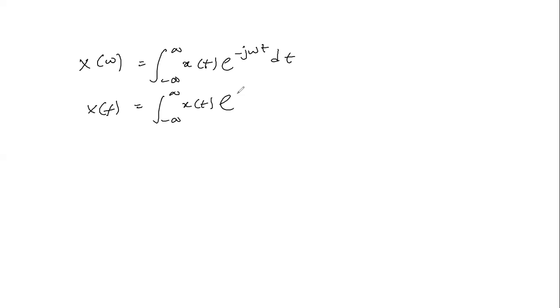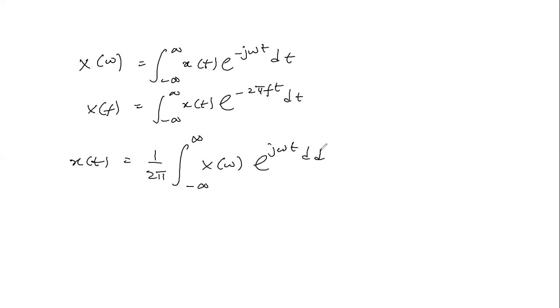Now, if that is clear, it means that our Fourier transform is the same as the integral from negative infinity to positive infinity of s(t) e^(-j omega t) dt. Okay. And we can also say S(f) will be the same as the integral from negative infinity to positive infinity of s(t) e^(-j 2 pi f t) dt. Okay, and the inverse Fourier transform follows directly: 1 over 2 pi times the integral from negative infinity to positive infinity of S(omega) e^(j omega t) d omega. Okay, and we also prefer to use our Fourier transform pairs to resolve our problems.